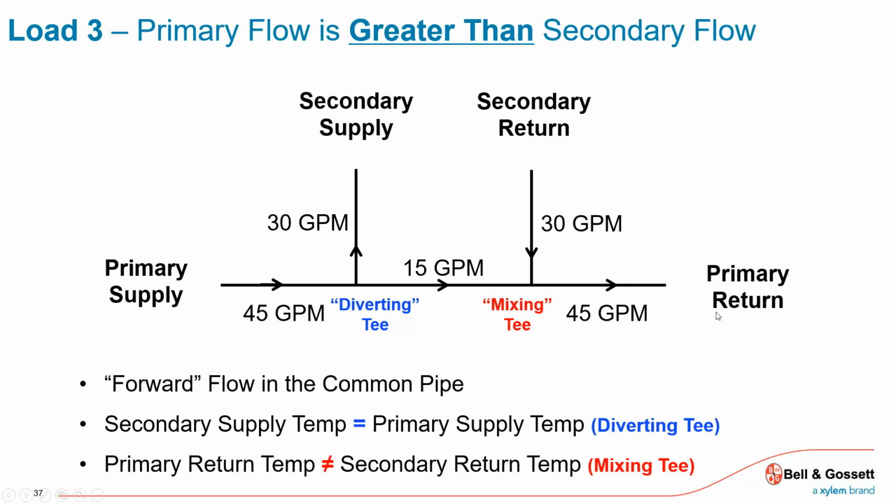So the flow rate will be equal, the flow rate will be less, or the flow rate will be more in the primary. Those happen all the time, whether it's pillars, whether it's multiple boilers. There's all different examples where that can occur. And the way it can occur with two different sets of pumps is I've decoupled those pumps so they almost don't even know each other exist, because that pressure drop right here between these T's is basically eliminated.